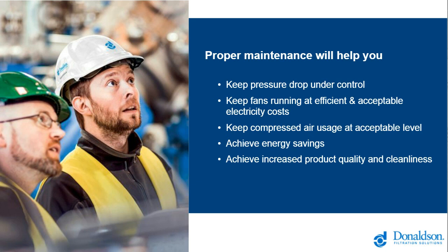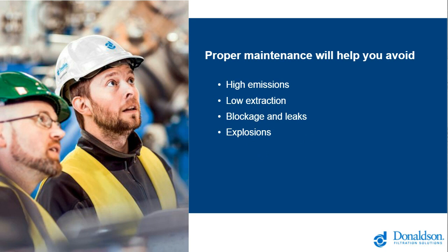As a second part, it will also help you avoid high emissions. You don't want high emissions. It will also help you avoid low extraction from the environment, whatever that environment is. And it will help you prevent blockage and leakage in connected piping. But even beyond that, it will help you avoid explosions because you can have dust accumulations, and there are lots of different dust types which are explosive.